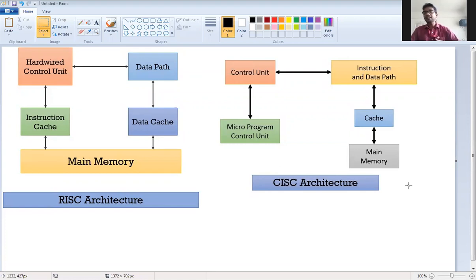Again, it has 4 ports, that is port 0, port 1, port 2, and port 3. It has two 16-bit timers. Then 6 interrupt sources are there. You know that the T0 interrupt is there, T1 interrupt is there, RI/TI interrupts are there, correct? The reset interrupt is there. Likewise, a total of 6 interrupts are there. It has 2 levels of interrupt priority, and it has power saving modes. Idle mode and power down mode are the two power saving modes available in the microcontroller 89C51.